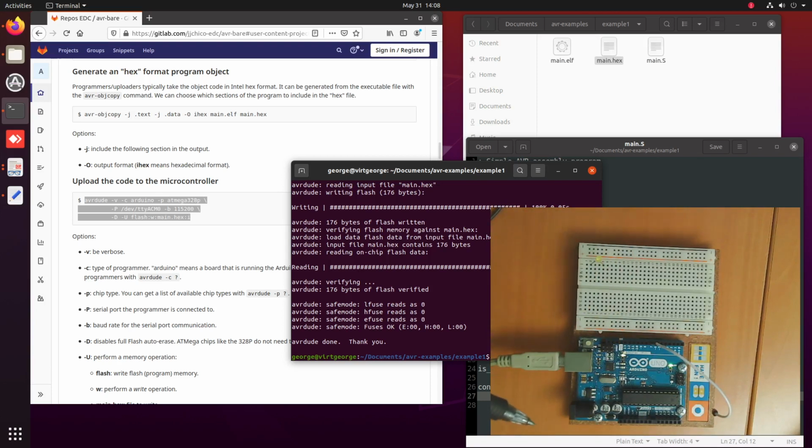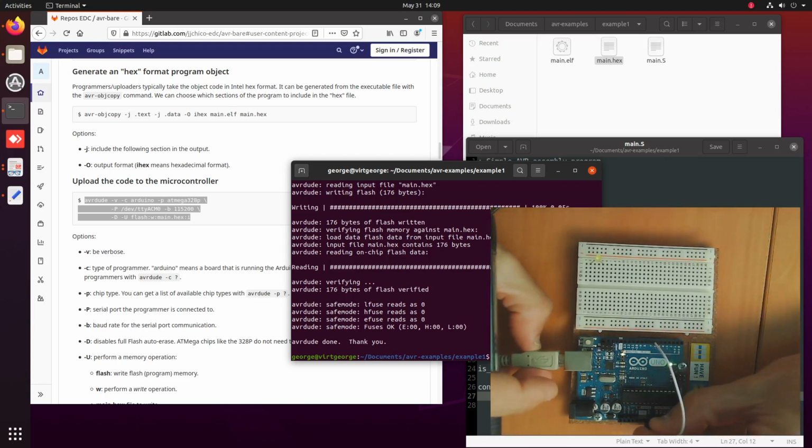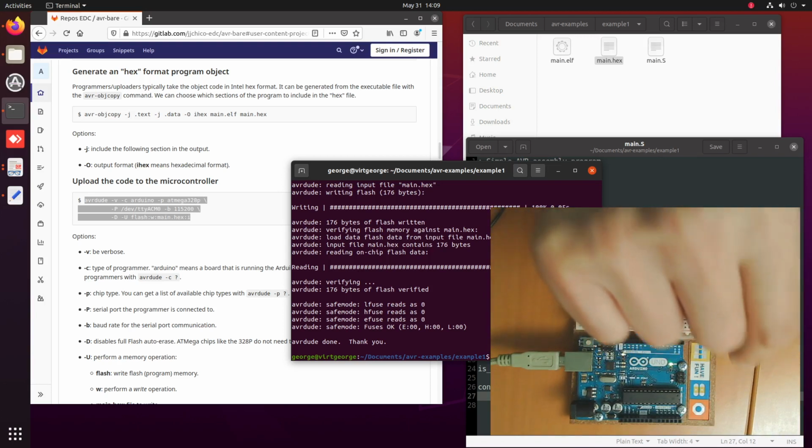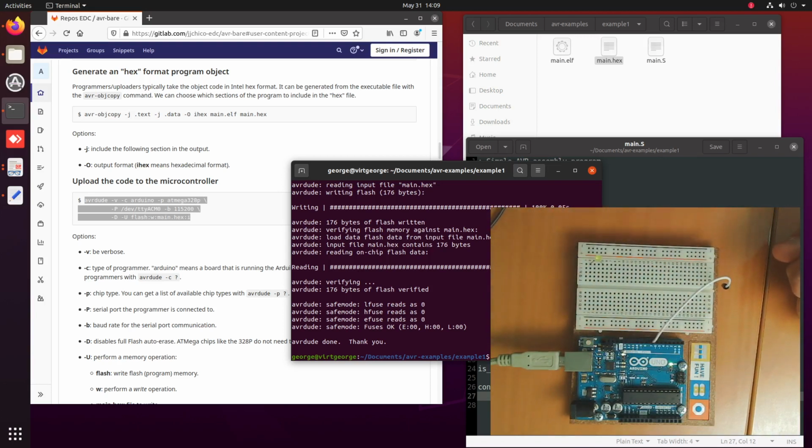So it's never left floating. It's very useful, because in that way, if we want a 0, we connect to ground, and if we want a 1, we just disconnect. This is very good, because if we want to drive this line with a push button, we can use a push button, and we don't have to add our own pull-up resistor.